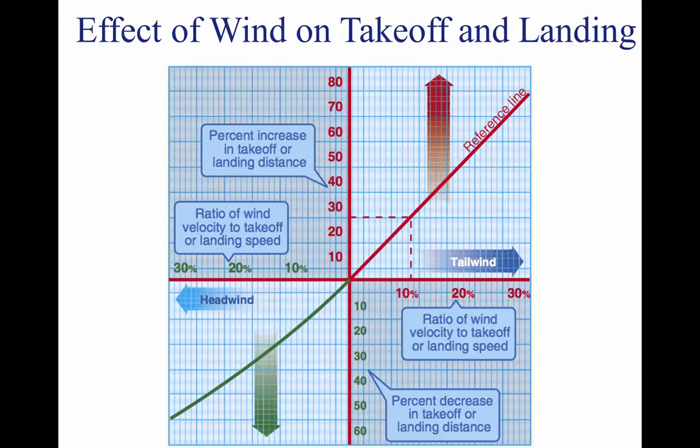In addition to the important factors of proper procedures, many other variables affect the landing performance. Any item that alters the landing speed or deceleration rate during the landing roll will affect the landing distance. The effect of gross weight on landing distance is one of the principal items determining the landing distance. One effect of an increased gross weight is that a greater speed will be required to support the aircraft at the landing angle of attack and lift coefficient. When minimum landing distances are considered, braking friction forces predominate during the landing roll, and, for the majority of aircraft configurations, braking friction is the main source of deceleration.